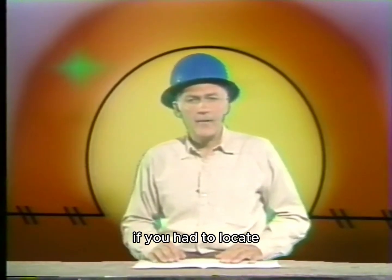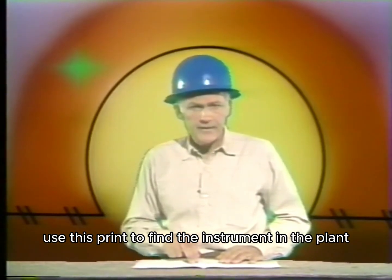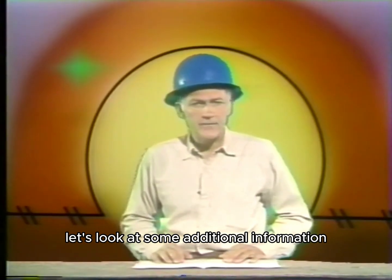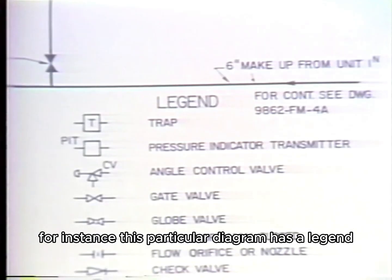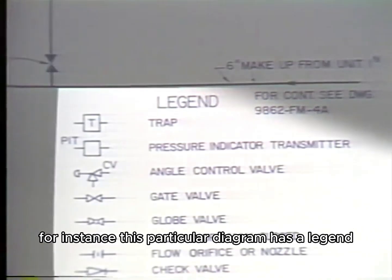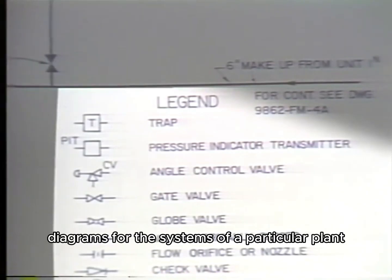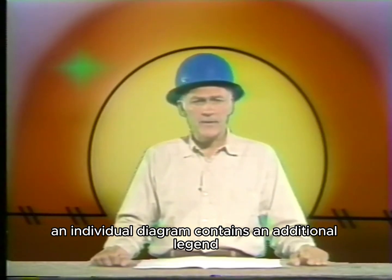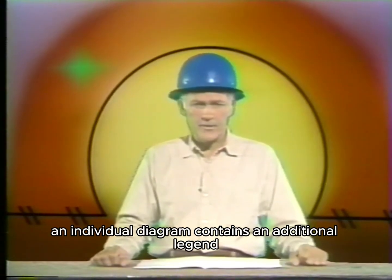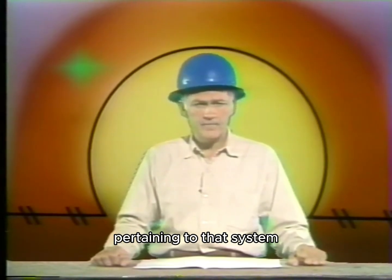If you had to locate and repair an instrument in the condensate system, you'd use this print to find the instrument in the plant. Let's look at some additional information found on this diagram. For instance, this particular diagram has a legend. Legends are usually found at the beginning of a set of diagrams for the systems of a particular plant. But often, an individual diagram contains an additional legend with symbols of specific instruments pertaining to that system.